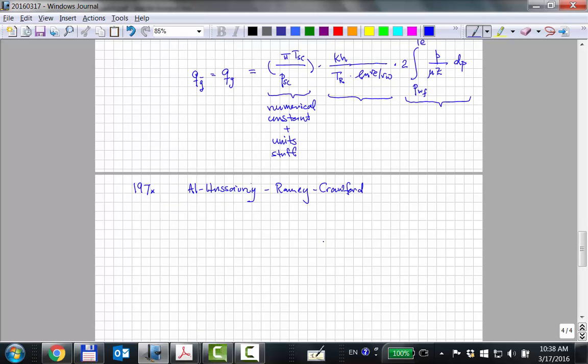So what they did is that they introduced what was at the time called the pseudopressure, the gas pseudopressure function. Okay? It was originally written m of P. Now the SPE requires you to write psi of P. It's just changed the terminology.